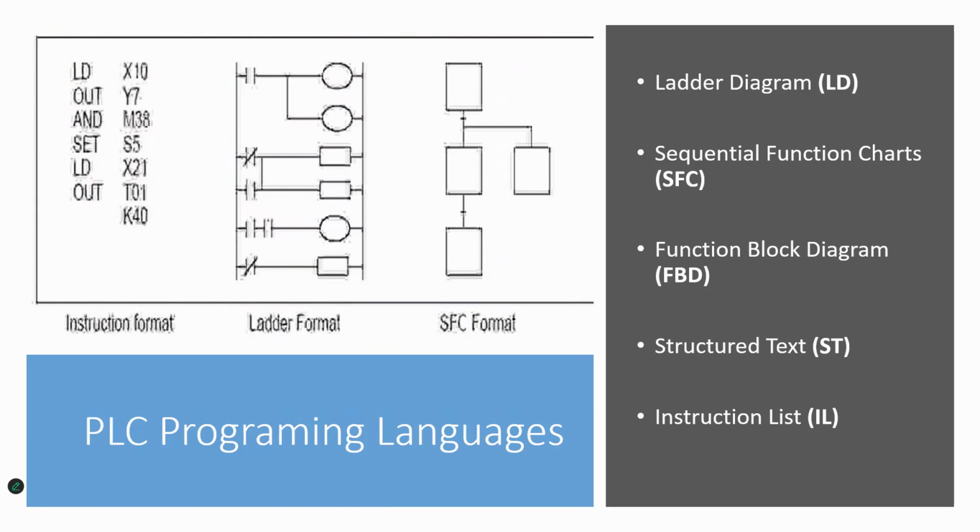Now, do note that with these 24-volt versions, for at least most of what I'm going to be talking about in the first section of the presentation, no PLC is included and the programming is not included. So, at least in the beginning section of this presentation, when we look at the individual modules, the end user will need to do the wiring from the model to the PLC connection board. You would, of course, have to have a PLC. You would also have to be fluent enough in one of these programming languages and have access to the programming language so that you can create the program that's going to be needed.